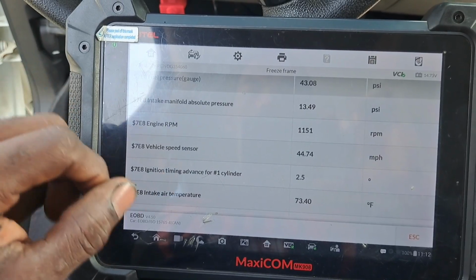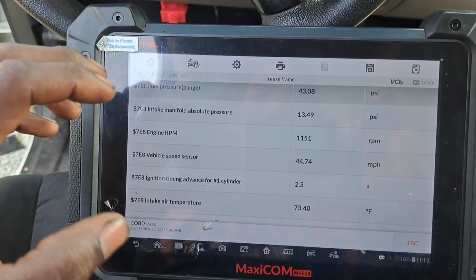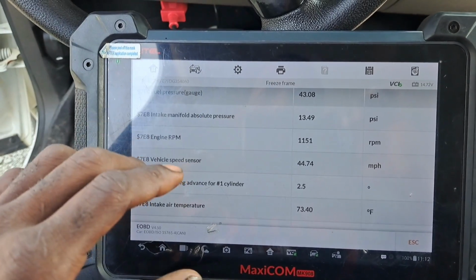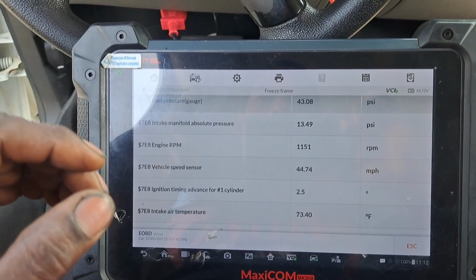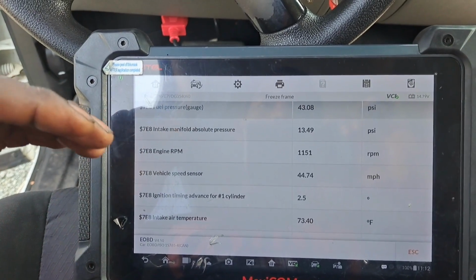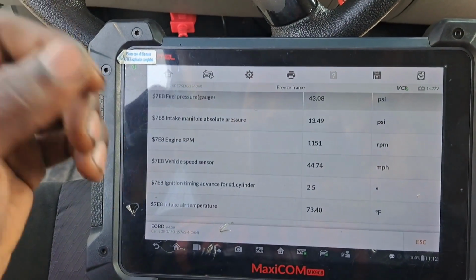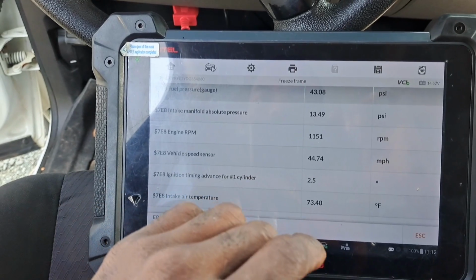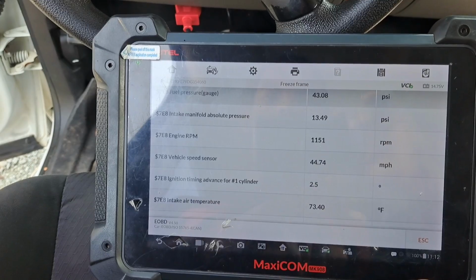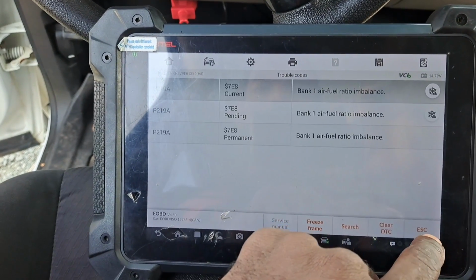From what I know about the fuel imbalance issue on newer cars, based off the 720-degree rotation, the vehicle can determine from the oxygen sensor falloff or peaks or valleys which cylinder has the imbalance. This car is a rudimentary system in comparison, and it doesn't have the capability to pinpoint the cylinder.